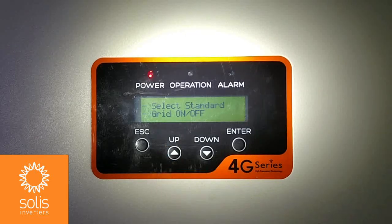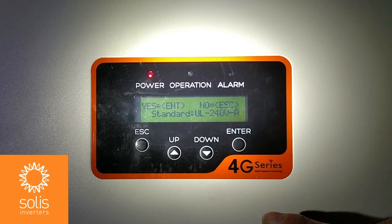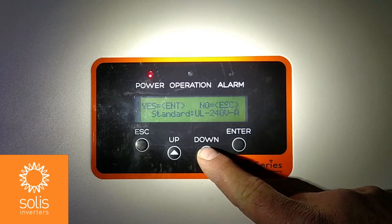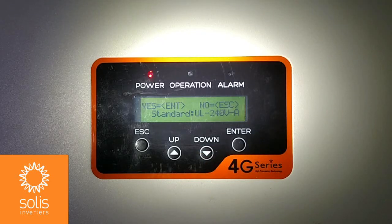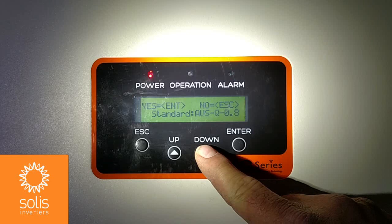So let's go up to select standard, go into there and see what we have it set at right now. Right now it's set for the UL North American standard at 240 volts, and you can see the -A there indicating the AFCI board is enabled. So now that the grid is off, I can go into set standard just using my arrow key, and now that I'm in the standard menu, I can use the up and down arrow keys to scroll through the standards until I find user defined.